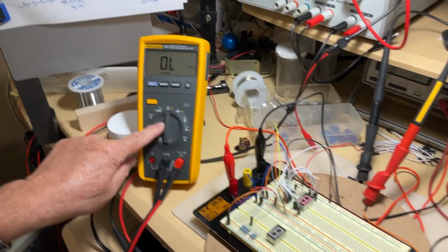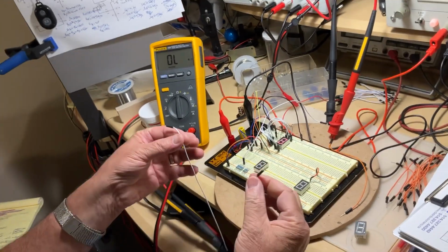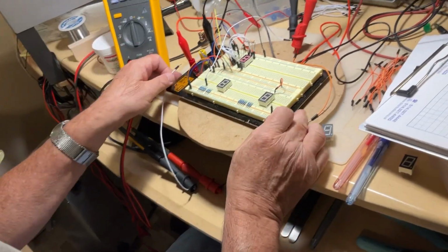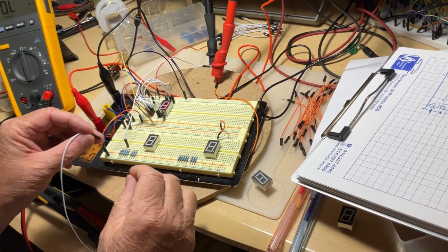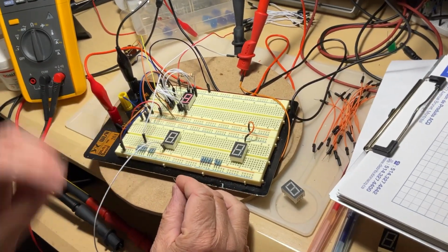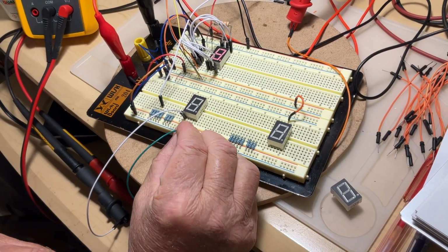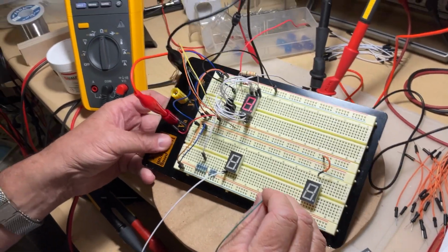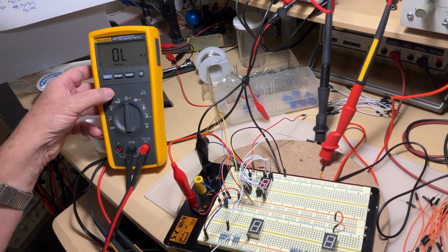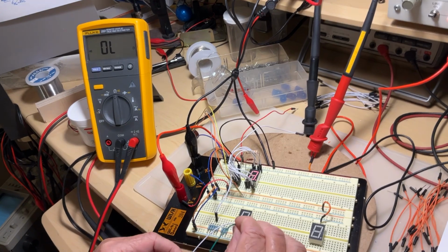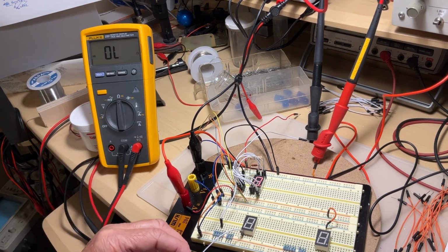I put my multimeter on Ohm-meter, and then I pick up 2 wires. For me, it's much easier to play it on a breadboard. I connect one to the pin number 1, and then I'm going to check the pin number 1 versus all the other pins of the package to find out if, by chance, there is a connection. Let's give it a sound. You see? Now when I make a short, it's going to emit a sound.